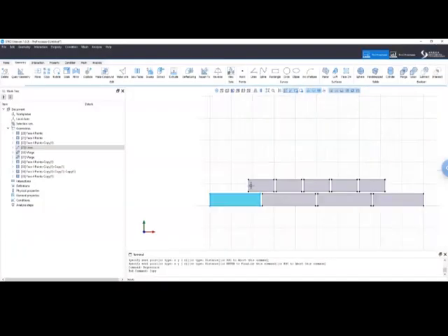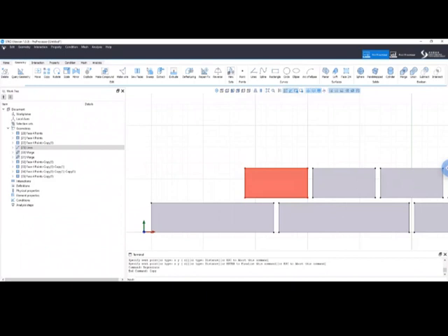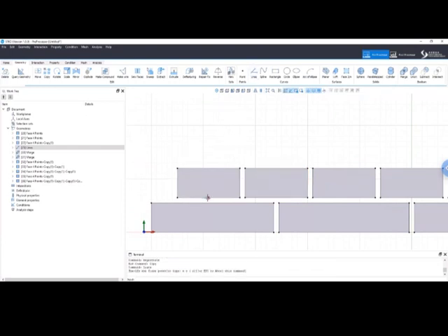So let me copy these here. Now let me divide it in 2. So I draw a line in the middle, but then I need to include half of the thickness. So I get the copy, or actually the move is sufficient. I select this line, and I move it. Let me look there. Okay, right click, and then I move it on the right of 5 millimeters.